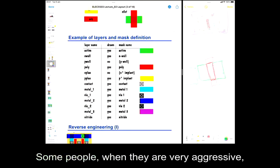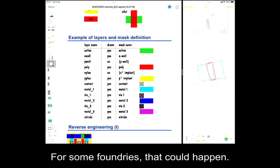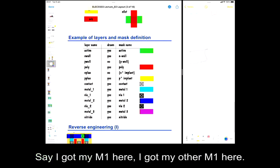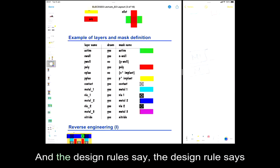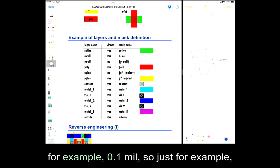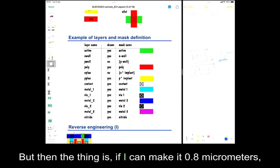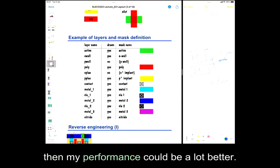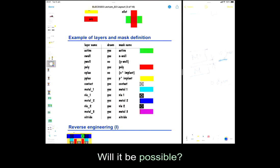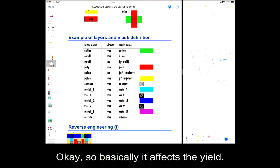Some people, when they are very aggressive, try to push over the boundary. For some foundries, that could happen. So, for example, say I've got my M1 here, and I've got my other M1 here, and the design rule says the minimum should be, for example, 0.1 micrometers. But then the thing is, if I can make it 0.08 micrometers, then my performance could be a lot better. Then you can file in and ask the foundry, I want to push it to the boundary. Will it be possible? They might say, for some rules they will let you do that, but for some rules they won't. Okay. So basically, it affects the yield.